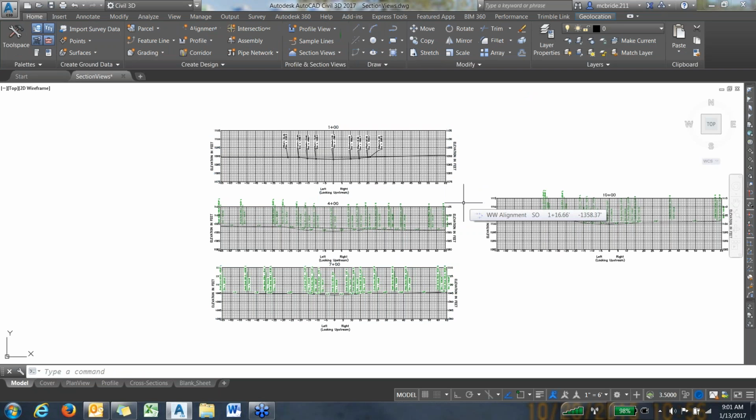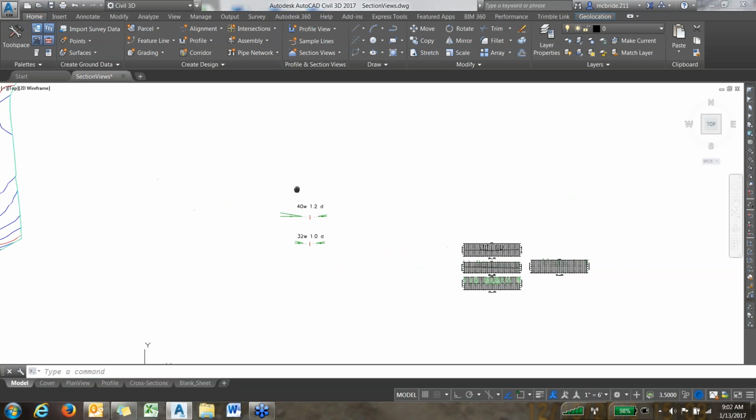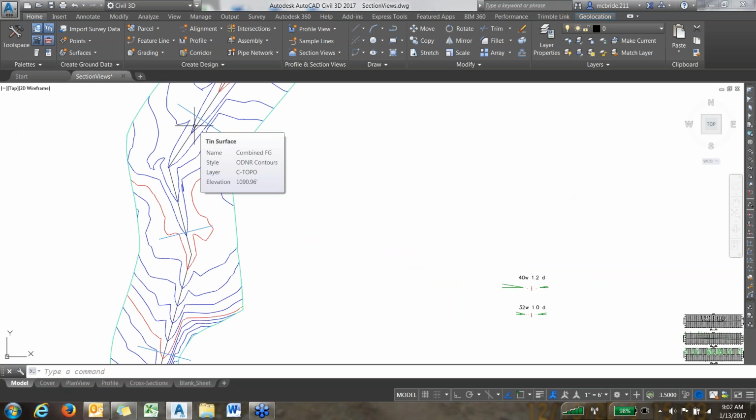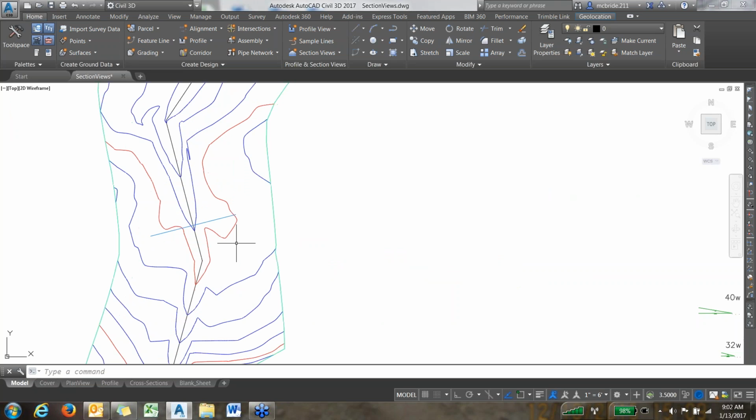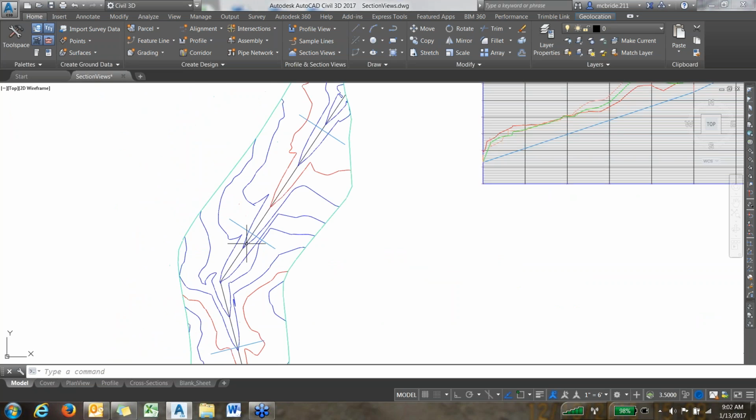There are a couple things you can do. Even at this point, you can change it as needed. So in the beginning, I taught you how to create sample lines. Okay, so let's go back out here to my sample lines. Each of these are 65 feet to the right and 65 feet to the left. I can change this at any time. Okay, so let's go up to station 400. Let's just use 100. That's what we've been working with.